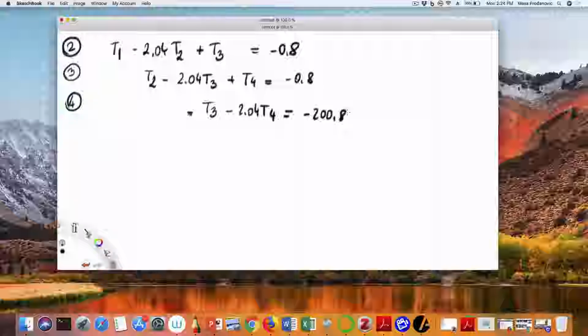And discretization means that I represent whatever differential operators I have. I use my values around me, and at every point I use the values around me to approximate the second order derivative, first order derivative, whichever one I have. And that gives me, ultimately, when I write that down for every point where I'm looking for the solution, a linear equation in the value that I'm at and maybe surrounding points. But 3 or 4 at most, depending on how wide is what we call the stencil or the numerical operator. Okay?